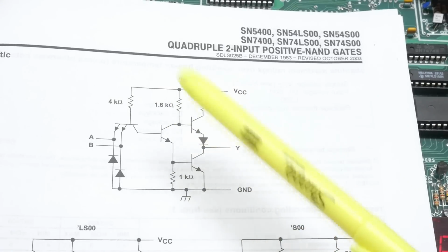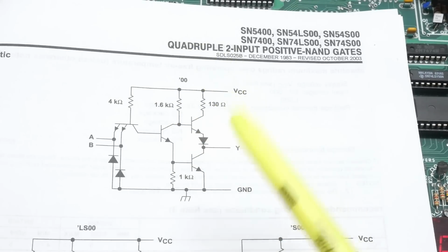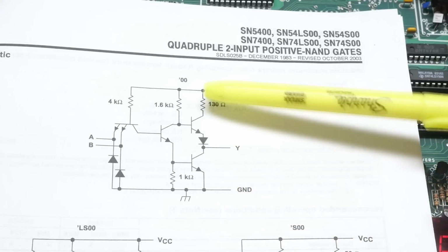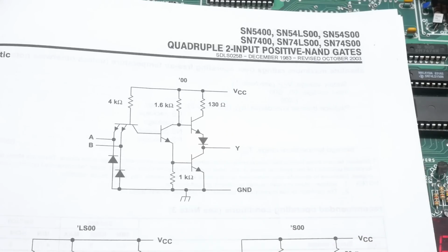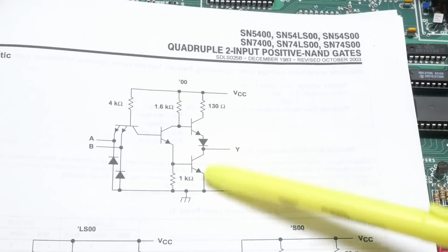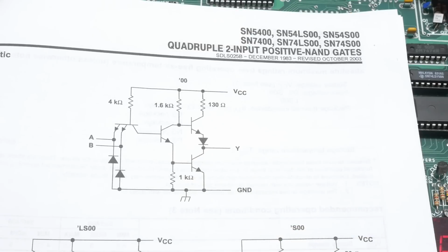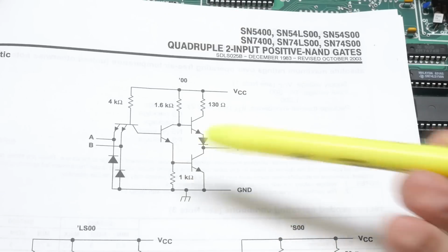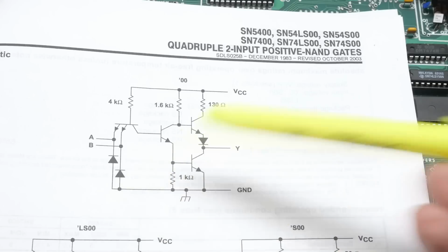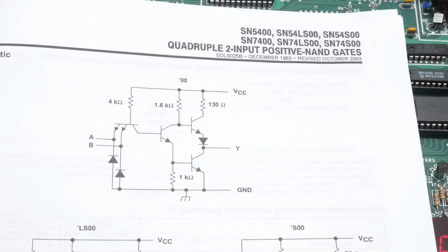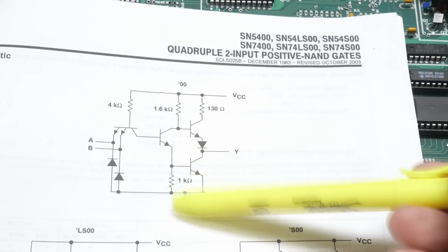All right, here is the gate of a 7400, a NAND gate. And this is the schematic of that NAND gate. And you can see that the output here has a transistor that can pull it low, a transistor that can pull it high. But you'll notice that they are bipolar transistors, right? CMOS hasn't been invented yet. And so what is the voltage drop of a transistor? It's called VSAT. So what is your saturation voltage of this transistor? Well, it's around 0.4 volts. As long as it's below 0.4 volts, your output specification is correct. So it could pull it down pretty good.